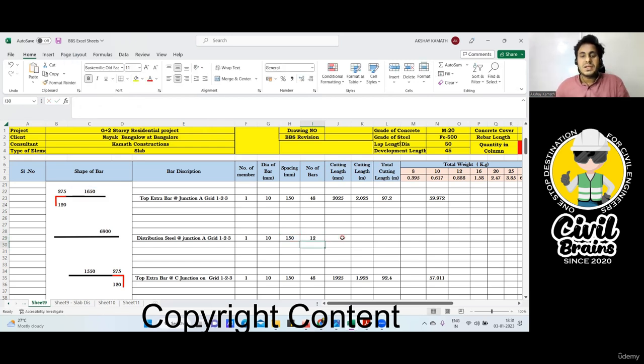Got it, no? After that, you can find cutting length. It's simple. This itself is your cutting length, and this I divide by 1000. Finish. And then total cutting length will be 6.9 multiply by number of bar, 12, multiply by number of member. Finish. This is total cutting length of all the distribution steel. And weight, since it's a 10 diameter bar, you have to put it in the 10 diameter column. 82.8 multiply by 0.617. Finish.